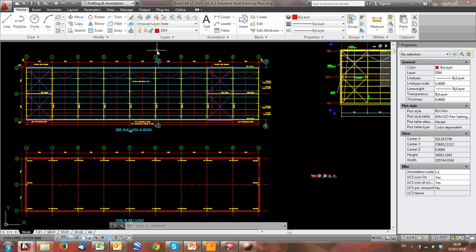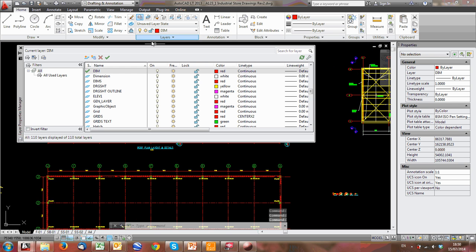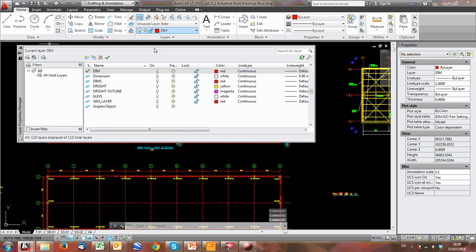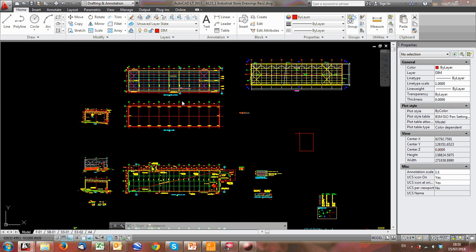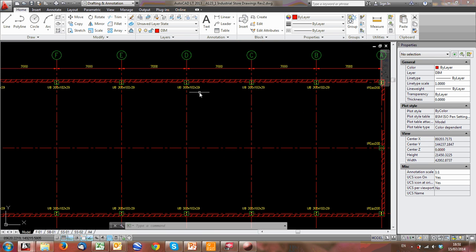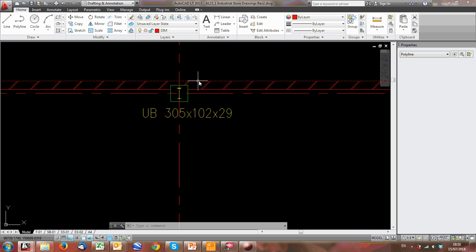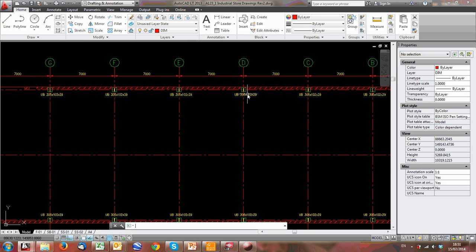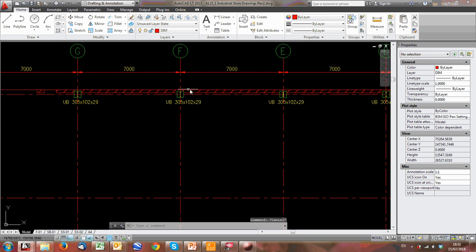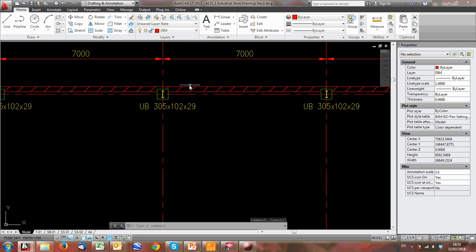Just to have another run through of layers, since they're so important, we discussed them previously, but if you click up here again, there's your layer properties. It's got all your layers inside, all the different colors, line types. You can edit line types. You can, however, manually change layer information outside of this. Let's say I've drawn this, and this is currently on brickwork. You can see now, even though this is brickwork, I can manually change it to be on another color.